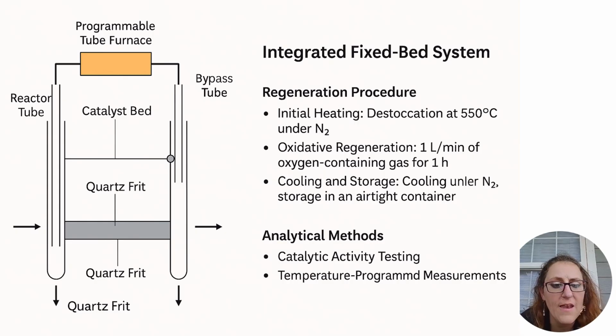Two key analytical procedures were conducted on the regenerated catalysts. Catalytic activity testing: the restored samples were immediately subjected to sulfur dioxide oxidation activity tests under standard operating conditions. This step quantified the catalyst's ability to convert sulfur dioxide to sulfur trioxide, providing a direct measurement of the regeneration effectiveness.